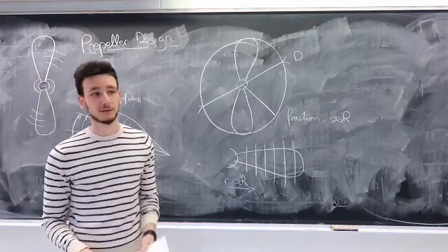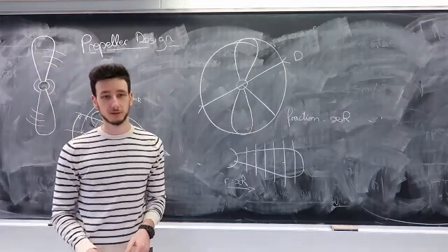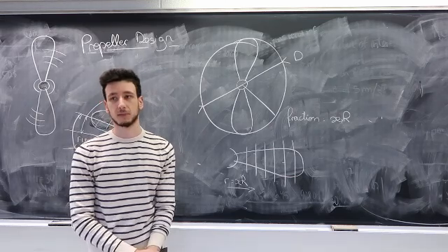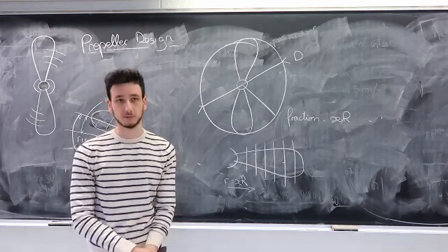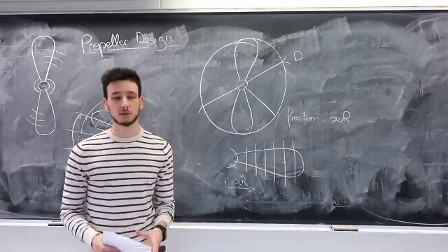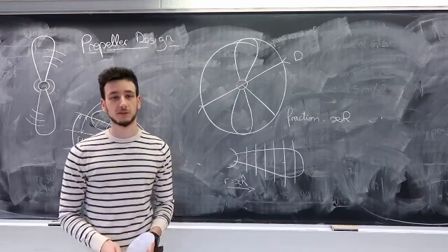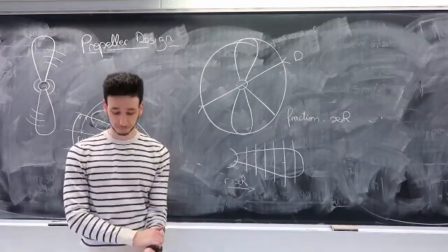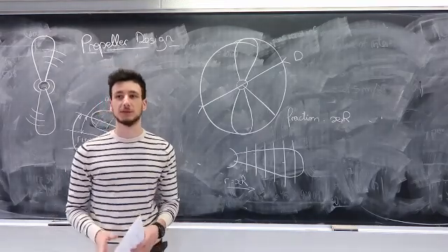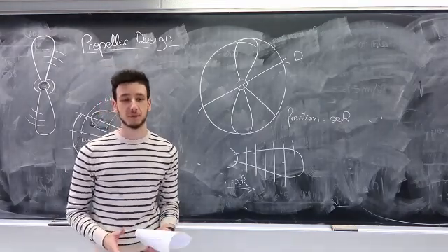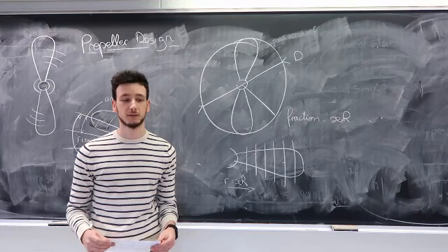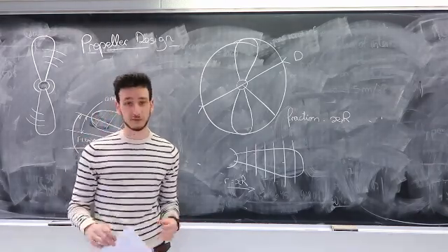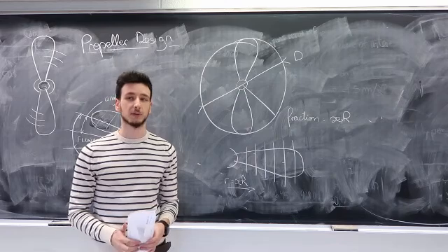For each section, we had to implement an angle of attack and a chord. We want maximum efficiency at J equals 0.25. We thought that we had to have an angle of attack for which the L/D ratio was the highest. And the chord was set by adapting a formula for another propeller, the McGill DTM 7557, which was an example in the book.